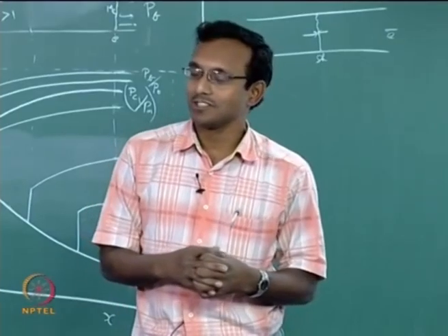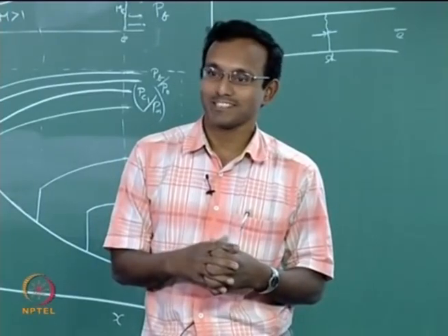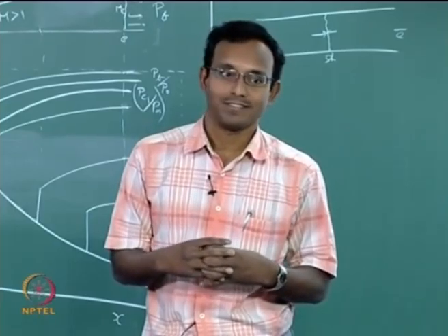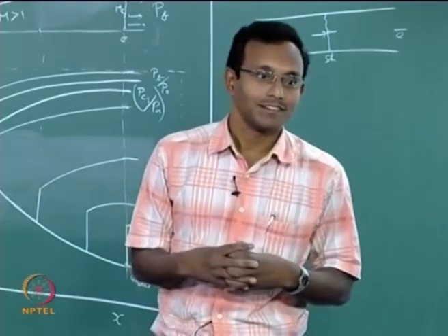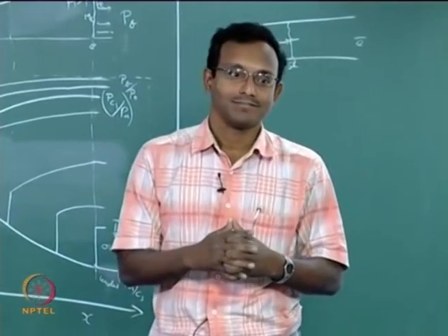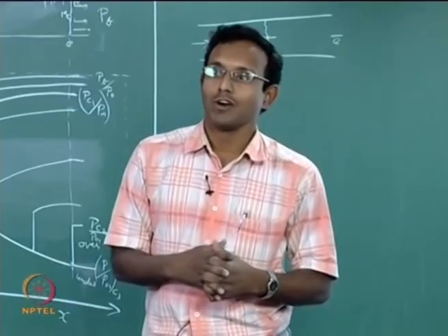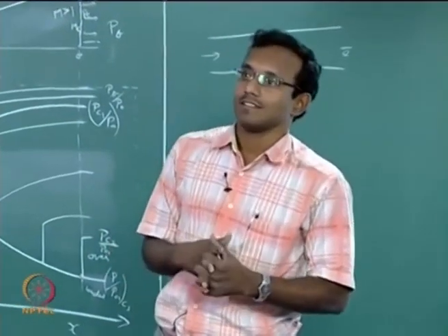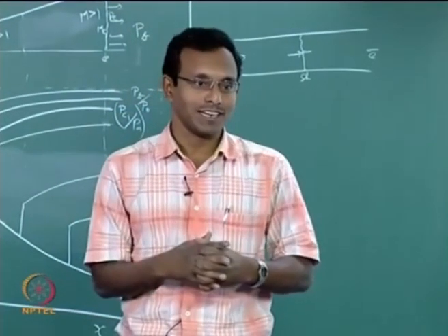When we say the strength of the shock, what do we mean by the strength of the shock? Strength of the shock increases. That is where the answer lies. What is that? To what extent it can make the flow subsonic, in the sense? Up to what extent it can make the flow subsonic? Velocity not very different. Probably you are talking about the Mach number jump, the delta M you are talking about.